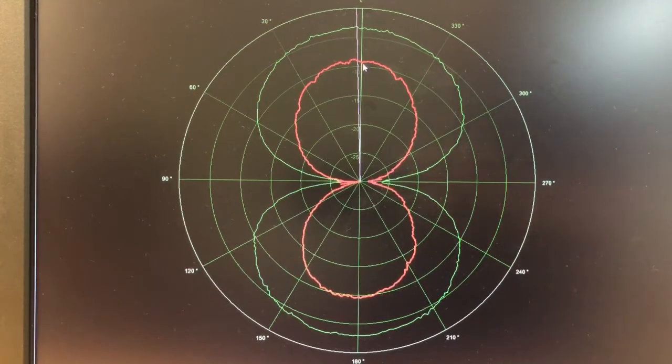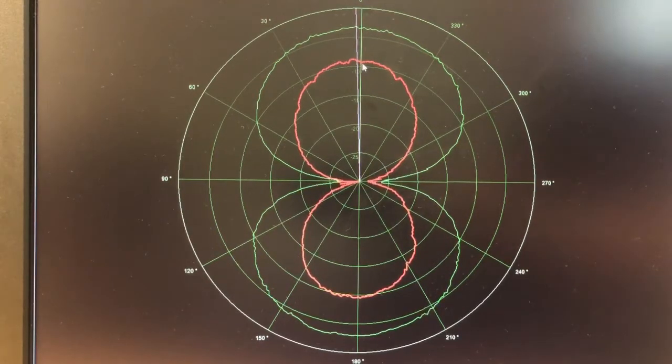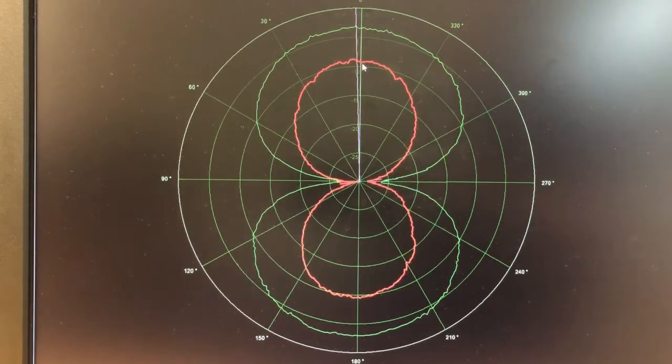So when we are doing that, the impedance mismatch at the port of the antenna also plays an important role. If you remember from the class, the 1 lambda dipole antenna has a very high impedance at the input port. So you're going to have some impedance mismatch, and because of that, as compared to the half wavelength dipole antenna, you get a smaller signal.